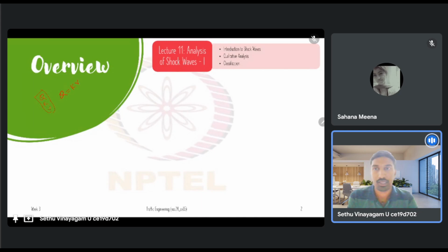Why? Because these three variables are related by this equation, right? So q is equal to kv. If you tell me the value of q and the value of v, automatically there will be only one value of k that will satisfy this equation. So in fact, you only need any two out of these three variables to uniquely describe a traffic state, right? So that's traffic state.